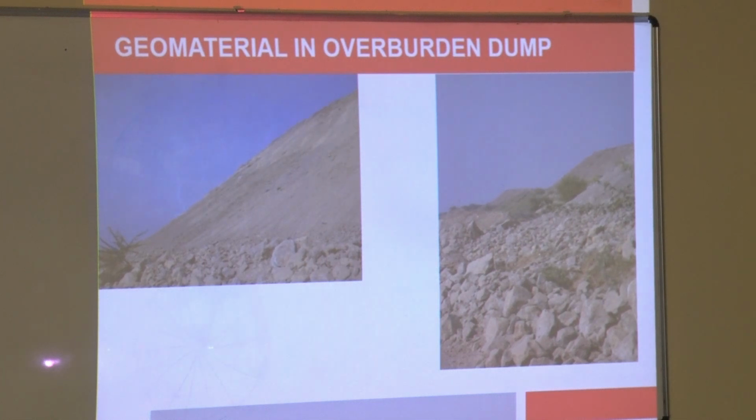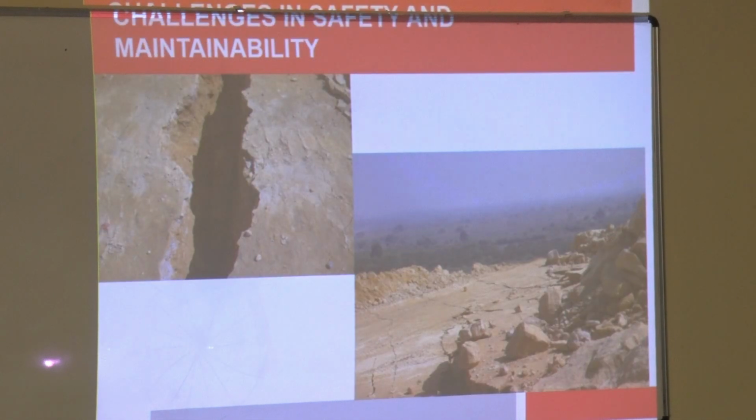That is why nowadays continuum based numerical methods, in critical cases, could not accommodate the failure generally observed in this kind of slope. That is why I will share one piece of information. Here you can see large cracks in the slope surface of the overburden dump.